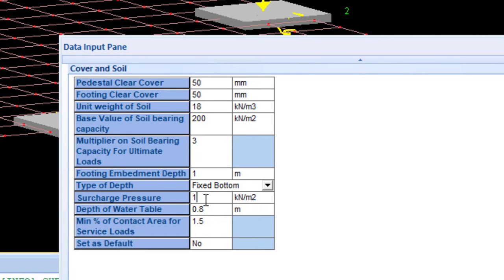So that's the essence of this. So if you say the water table gets to the top or the surface of the foundation, the software will be able to check the effect, the extent of uplift. When the water table is high, is it going to uproot your structure? It's going to affect the stability. So that's the essence of this water table.